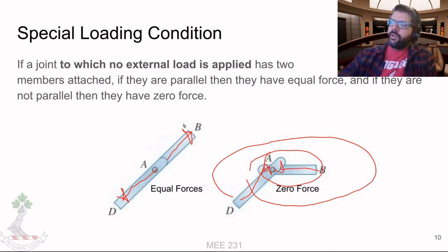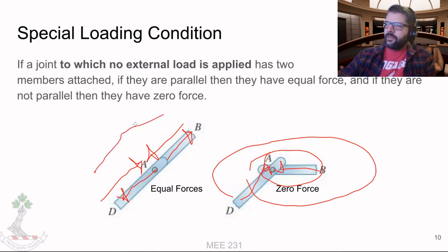Because if you're trying to hold a compressive load like this, the instant you had any tiny little deflection or tiny little movement, then it would shift somewhat, and then they'd no longer be parallel, and then it would collapse in upon itself, and your bridge would collapse, and a lot of people would die. So don't try to do something like this to hold a compressive load.